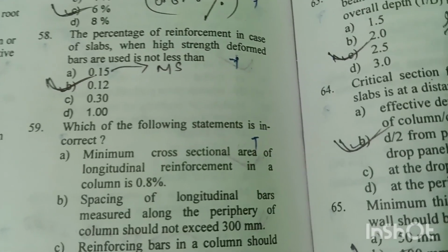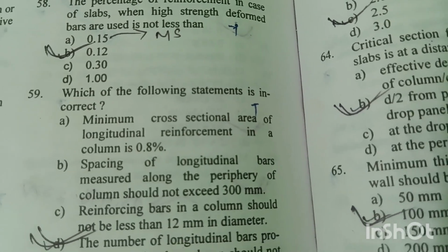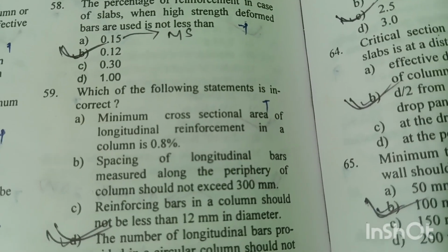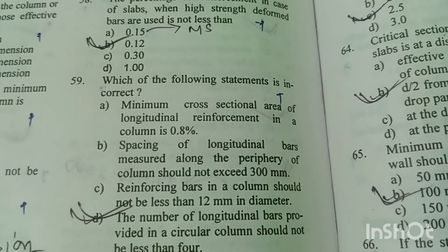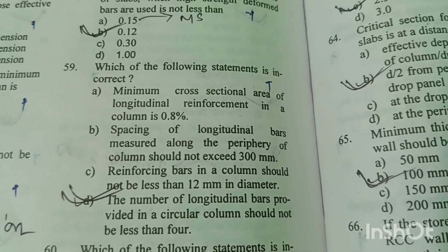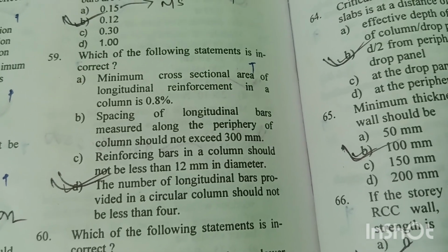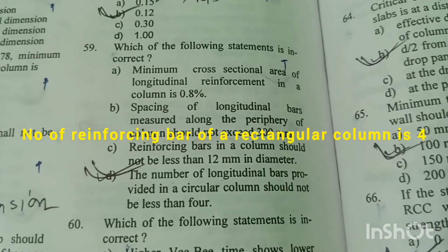Question number 59. Which of the following statements is incorrect? Statement A. Minimum cross-sectional area of the longitudinal reinforcement in a column is 0.8%. Right. Statement B. Spacing of longitudinal bars measured along the periphery of the column should not exceed 300 mm. Right. Statement C. Reinforcing bars in a column should not be less than 12 mm in diameter. Right. Statement D. The number of longitudinal bars provided in a circular column should be less than 4. No, it should be at least 6. So statement D is incorrect.